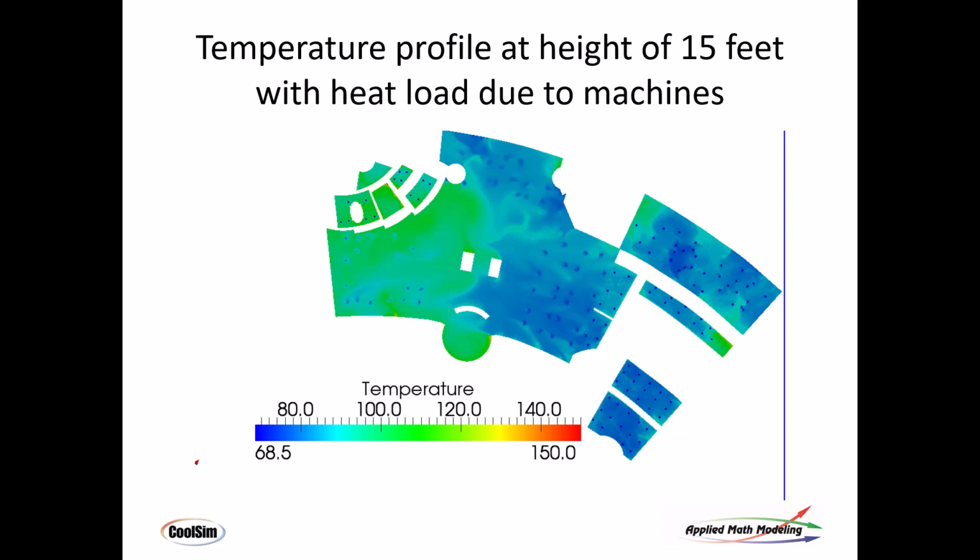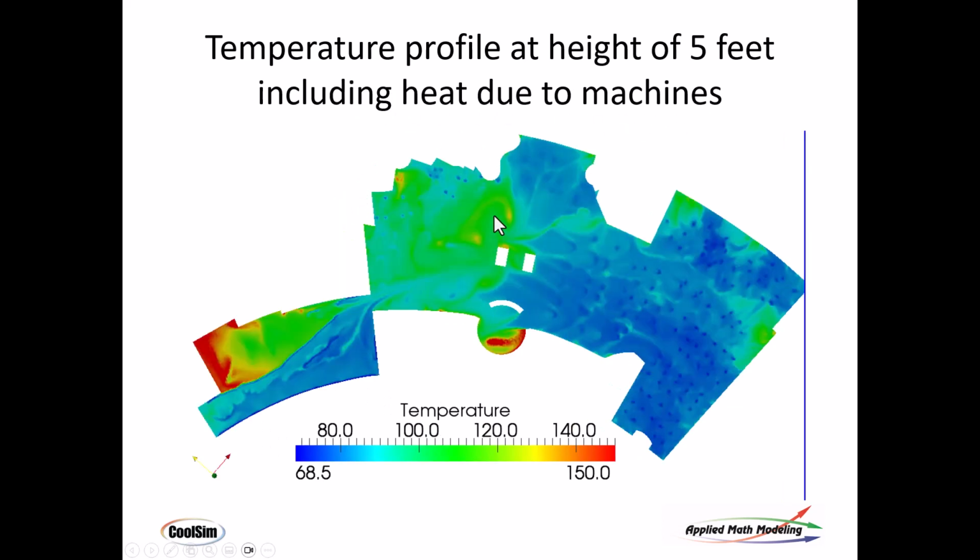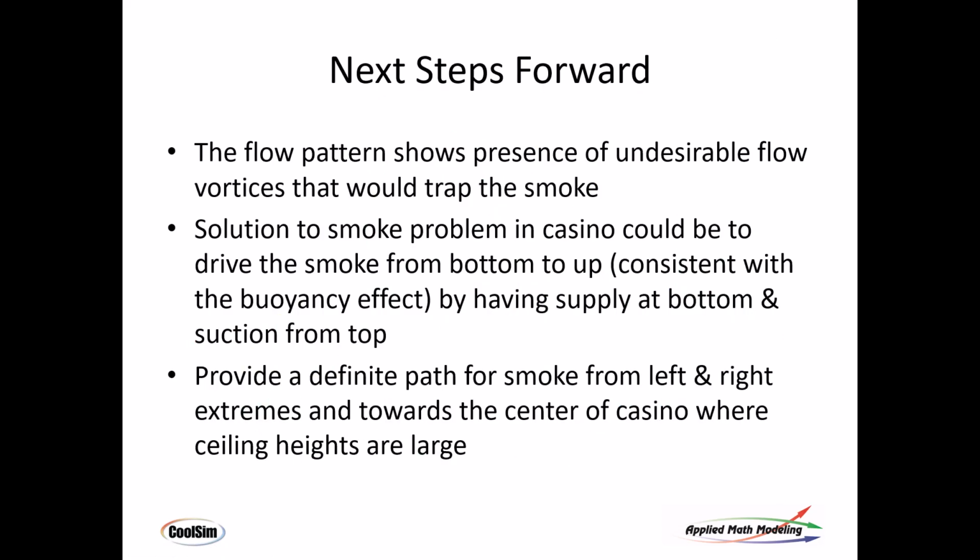Temperature profile here at 15 feet. Heat load due to the machines in the room. We actually modeled the heat load coming off of those gaming machines and put that into the room as a heat load, as well as the people. Temperature profile here. So once we had this all set in place, we were able to then make modifications to